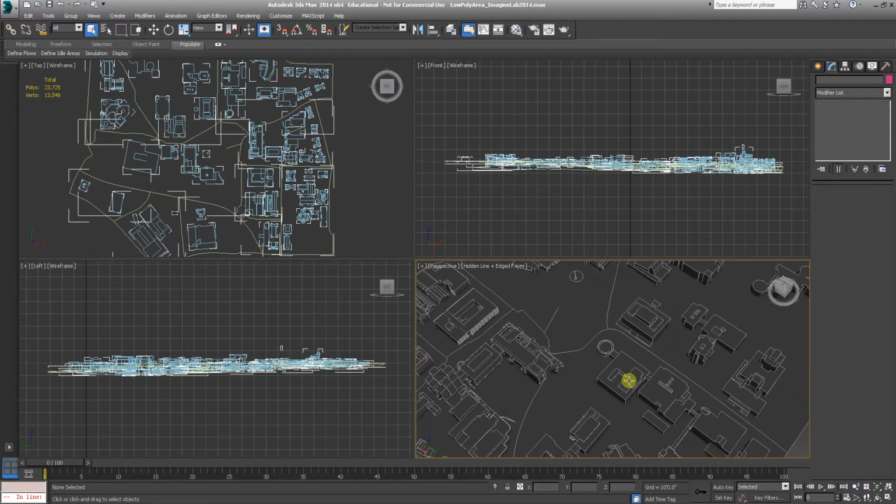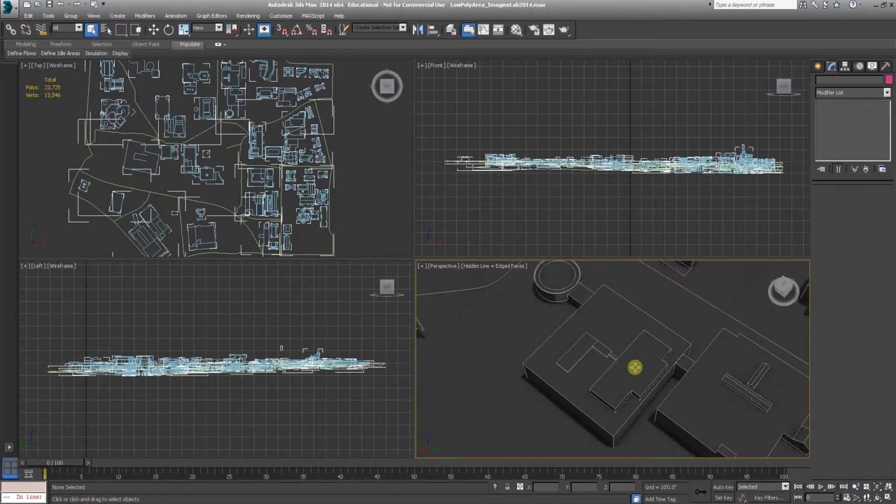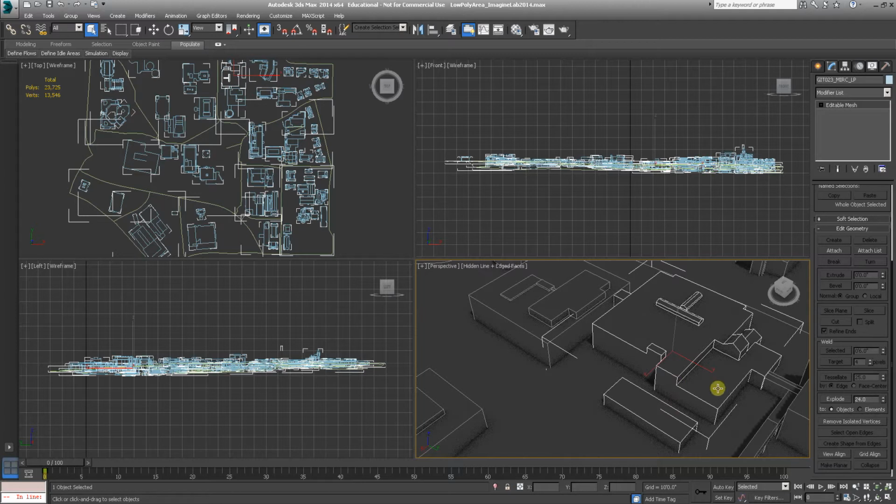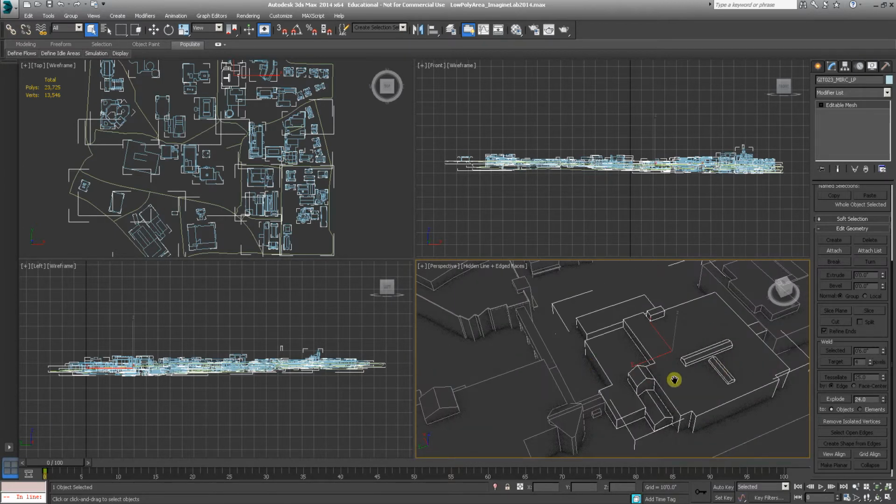So basically what you're going to do, and I would work at a 1:1 scale. If you scale this down to a 64th of an inch equals a foot, it's going to be really difficult because your tolerances of the 3D model's distances are very difficult to work with. Same with the viewport clipping. It will clip out. You won't be able to see the whole model. So clean these things up 1:1.